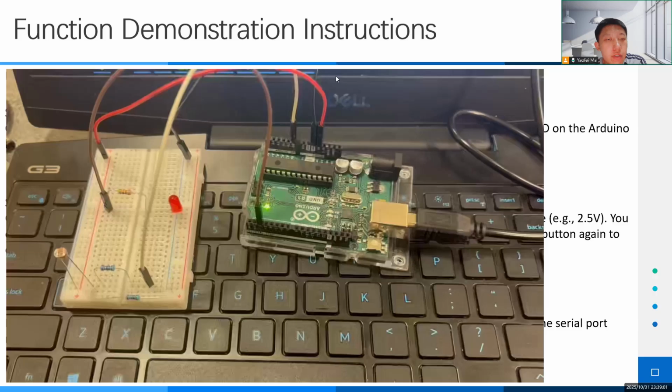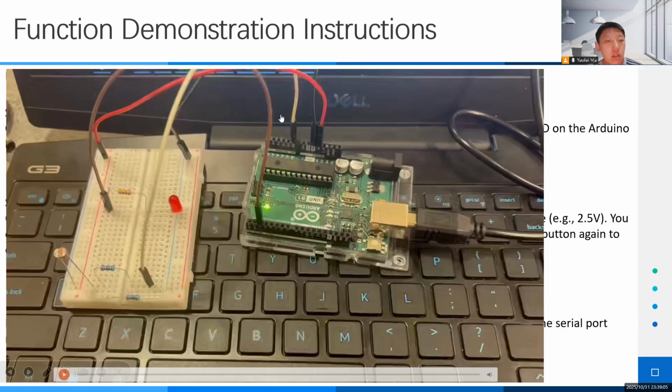Important precautions. First, upload the C++ code to Arduino first using the Arduino IDE. If not, Arduino won't understand the C# commands. Check the default port in C#. Make sure it's the same as the Arduino port in Device Manager.